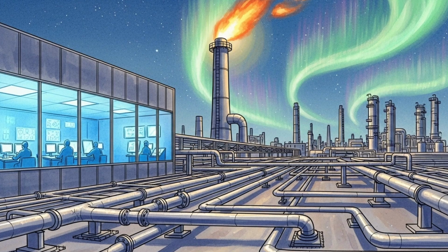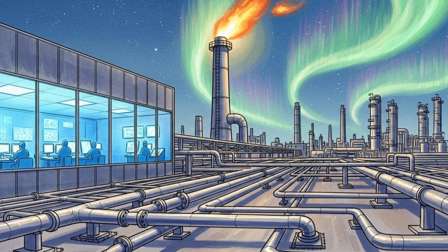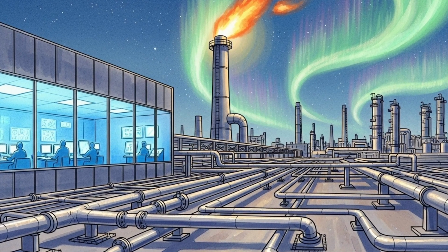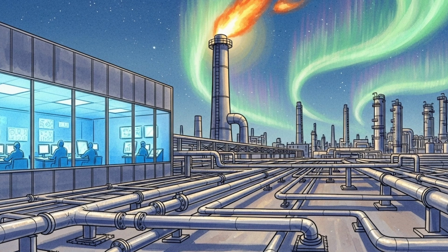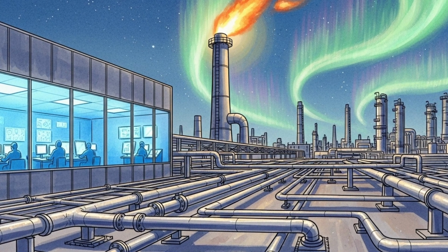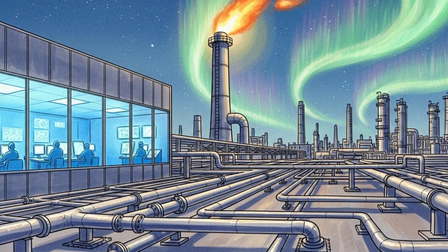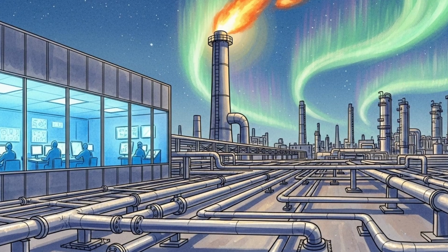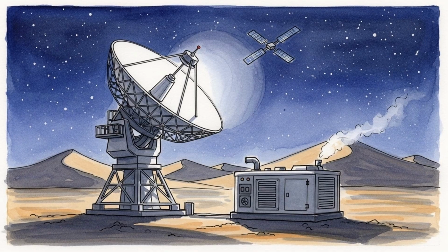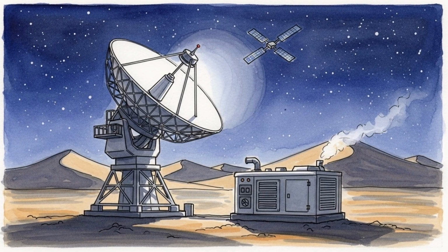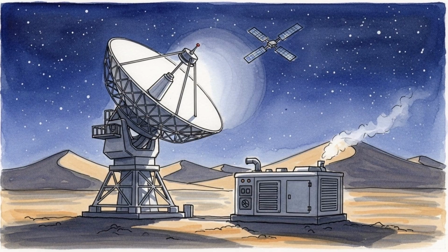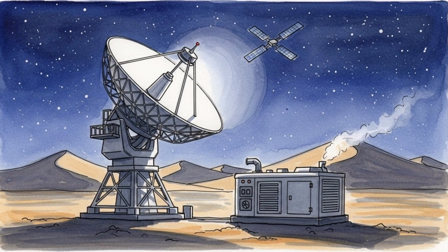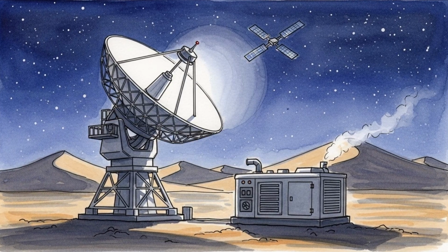Undersea fiber cables carry data on glass and are immune to induction in the fiber itself. However, repeaters along the cable need direct current power delivered on metallic conductors. Geomagnetically induced voltages can appear on these long return paths and cause protective actions or alarms in the power feeding equipment.